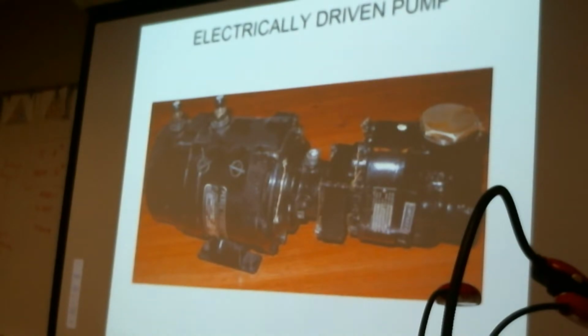Some of the hydromatic propellers that we had on older aircraft had to be feathered. You have to feather the propeller for emergency purposes. This was the pump, or actually even just changing pitch on a hydromatic propeller. So these are electrically powered pumps, but they provide for pitch change in the hydromatic propeller. They also allowed you to feather the propeller too. Well, they've been repurposed for another purpose.